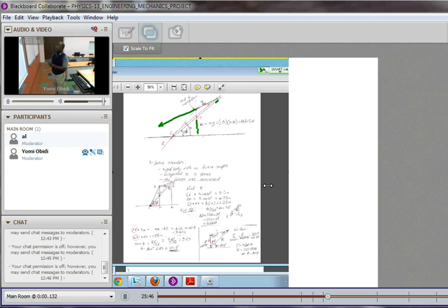So this is a three-force member. And remember, a three-force member, one that is a rigid body with no force couples, is subjected to three forces, or forces that are reducible to three forces. And those forces are either acting concurrent or they are all parallel. In this case, the forces act concurrently. There's this weight acting straight down, there's this tension, and necessarily the reaction has to pass through the point of intersection of the tension and the weight. So this is a three-force member, and we will use the three-force member property to solve this problem. Okay, let us proceed.